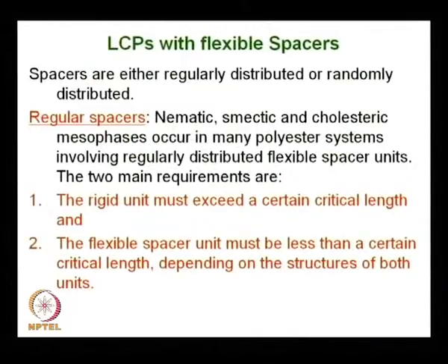LCPs with flexible spacers, as I showed, spacers are either regularly distributed, spacers means some unit placed between two rigid units, that is called spacer. If that is flexible, that will decrease the melting temperature. Say compare polybutylene terephthalate with polyethylene terephthalate.